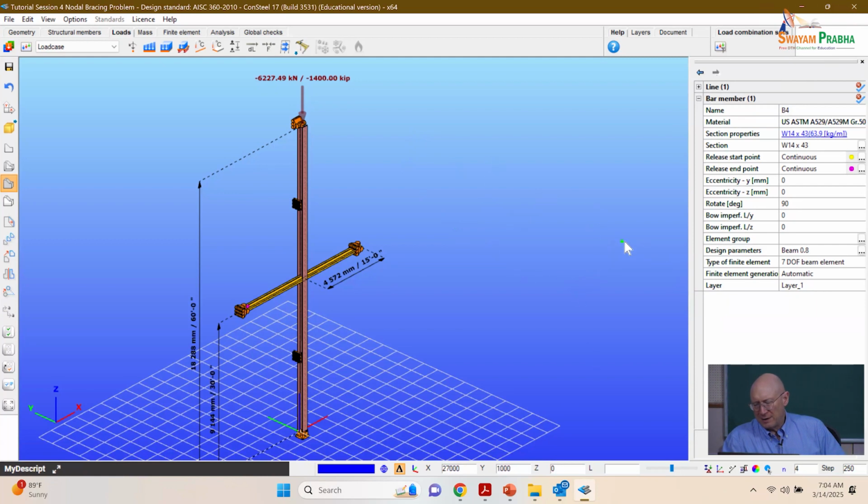In Consteel, for this problem, if I do an analysis where I model a perfectly straight column and a perfectly straight flying beam, and I put axial force on it, am I going to get any force in the brace? It's just going to go straight down the column and stay straight, right? So that's the problem once we're trying to do stability bracing, fundamentally.